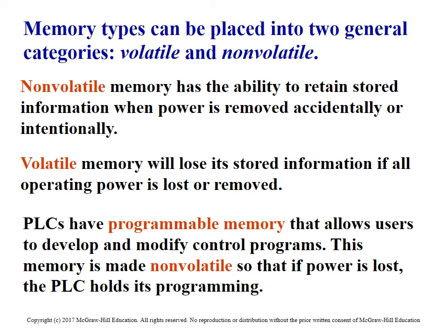Probably some of you have experienced some of this with your laptops or personal computers where you lost your battery, you lost some information because you lost power. Kind of the same idea. Most of our modern PLCs have a flash memory now. So before they lose power, they flash all the memory and store it on the PLC, so that information is stored before it loses power.